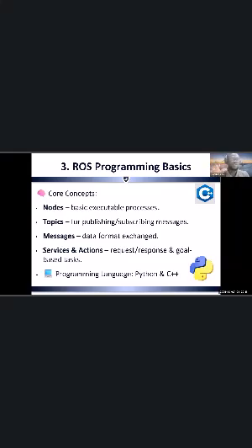All right, so messages, so subscribing messages. Messages are the data in the topic. For example, in the scan topic for LiDAR, you have numbers, a kind of data format exchange. I will explain this during the workshop. We'll echo a topic, so we'll do a ros2 topic echo /scan. I'm just dropping some commands we'll be trying. Then services and actions. When you want to do something in navigation, you can send a goal, and ROS services enable this.